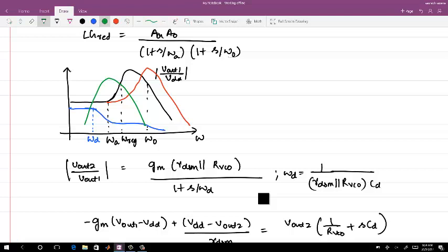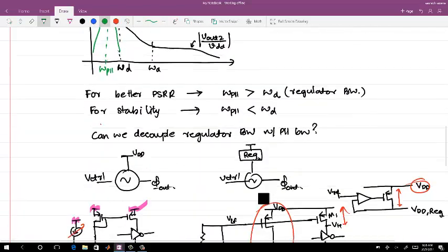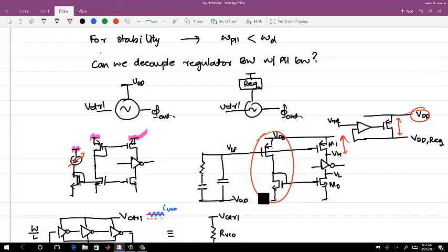You're not getting the benefit which you get by having an extra pole where you suppress the ripple a lot. So you can surely do that analysis of whether investing more power is more beneficial or splitting it as a replica gives you more benefits. And in the replica bias one, you will surely have matching issues. This is as good as the replica matching is. So you cannot always make a 1:1000 ratio if you want to reduce power. That will not be good. Okay.